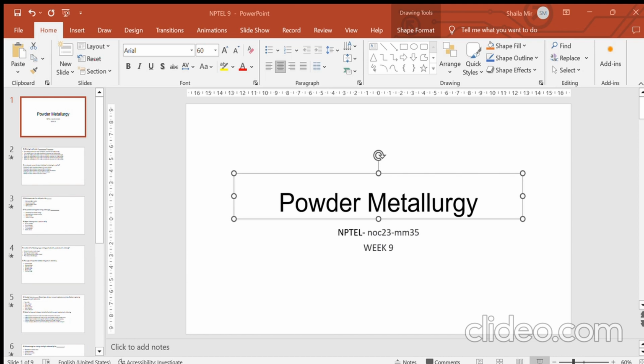So it is saying it is performed at the melting point of the major constituents, so that the final strength is increased. This is right because we need to increase the final strength of the compact that we are producing. The second option is that it is carried out at the melting point of the major constituents to decrease the final strength. This is wrong because we want a higher final strength for the compact. So all the "decrease the final strength" options are wrong because we are trying to increase the final strength.